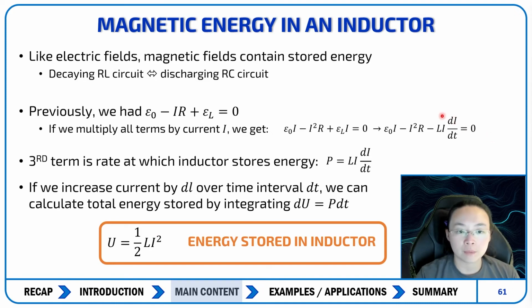So the third term, Li di over dt, is the rate at which the inductor stores energy. So we call this P. If we increase the current by dI over a time interval dt, we can calculate the total energy stored by integrating dU equals P dt. So we end up with U equals 1/2 Li squared to get the energy stored in an inductor.